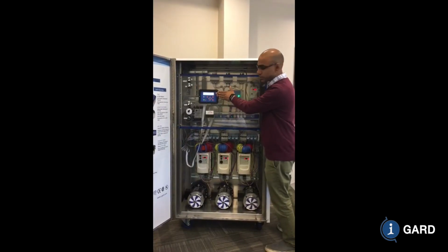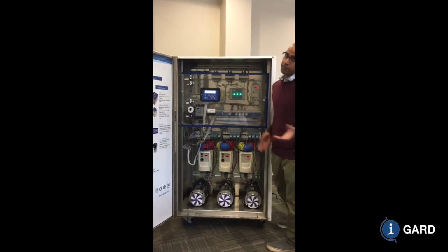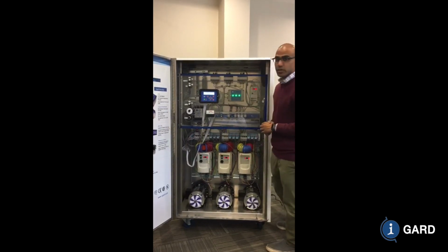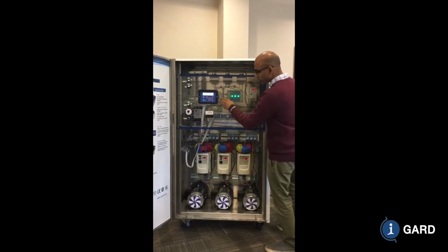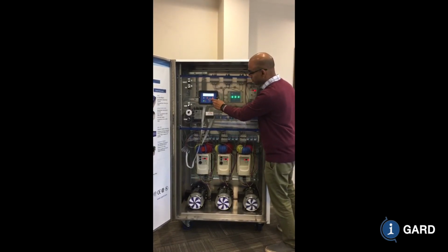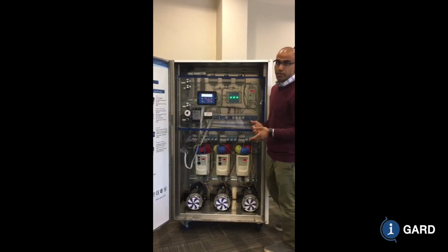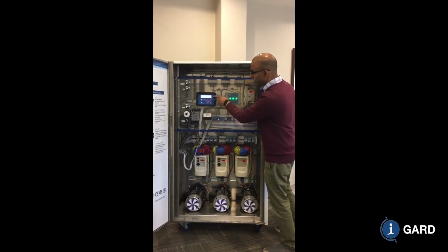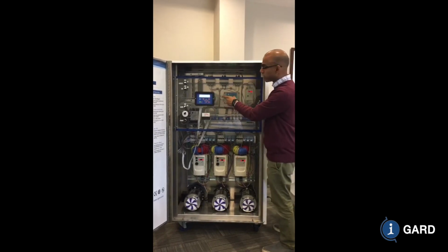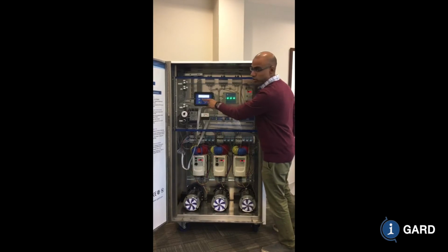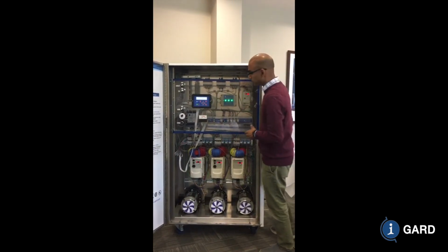The first is the home page. On the home page, it will give you HRG system okay if the system is okay. And if it's an alarm, this page will automatically turn to alarm. When you hit the right button from here, you'll go to the system page, which tells you a little bit about the system. It'll tell you how much fault current is presently on. Here it's saying that there's no fault current on the system. And it tells you what the alarm level setting is. Here it's at 50%. That's the default setting.